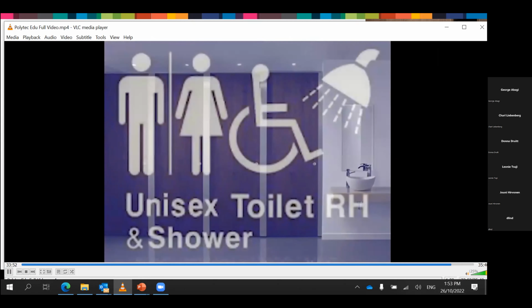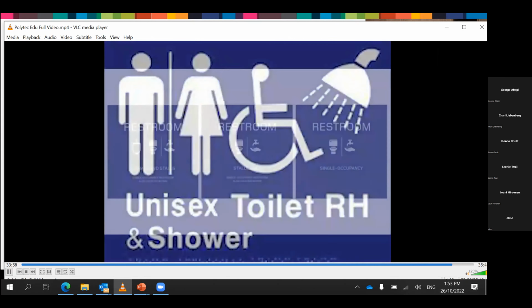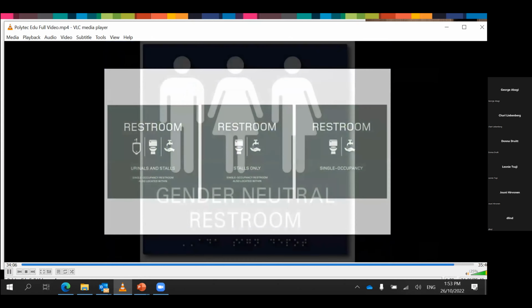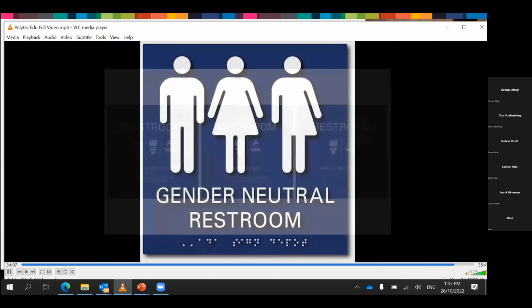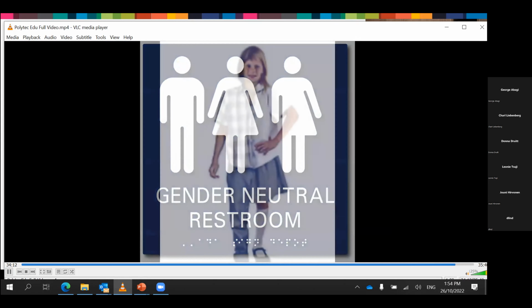In accordance with BCA requirements, accessible facilities must be unisex. As gender-neutral toilets are outside of the prescriptive requirements of the BCA, one can look at the design from a performance base. The use of gender-neutral signage also differs from what is set out in the current BCA.